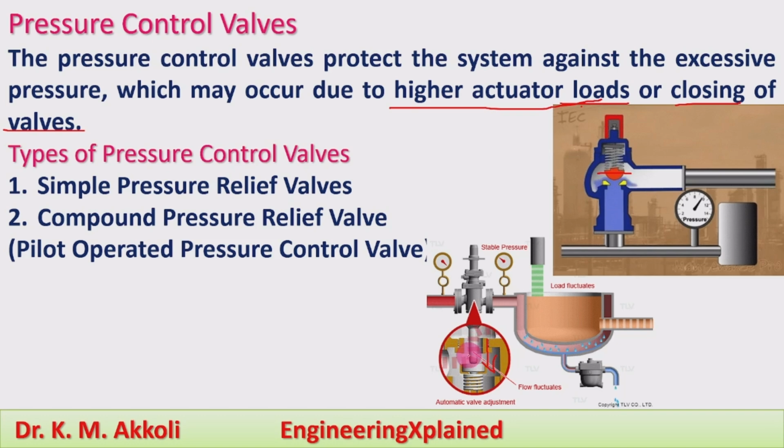That will reduce the pressure in the system. If the pressure is less, it will not be released, or the flow will be reduced. Based on that, another pressure line is used here, which varies the bypass flow to reduce the pressure. Whatever the pilot operation means, we are going to use another flow line in the system, another pressure, to operate the pressure control valve.